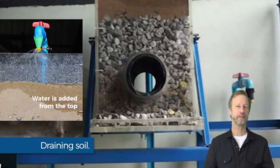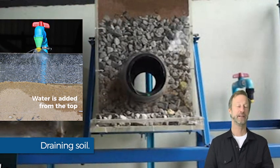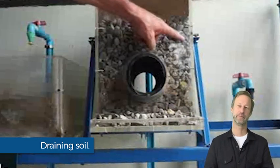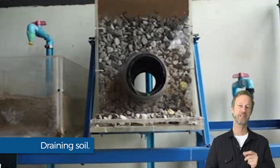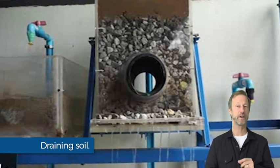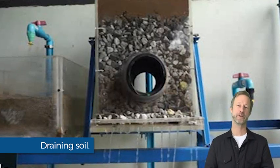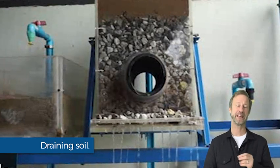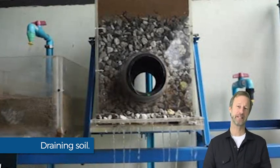We can follow the water down through the sand. As it moves through the sand, it's traveling by capillary, so no movement of the sand particles can be observed. Movement through the drain rock layer is more rapid since the spaces between the rock aggregate are so large. At this point, movement of the water changes from capillary to flow since there are large open spaces for it to flow. This is also washing particles of sand to the bottom of the container where they will begin to build up. Water is now visible coming out of the bottom of the container.